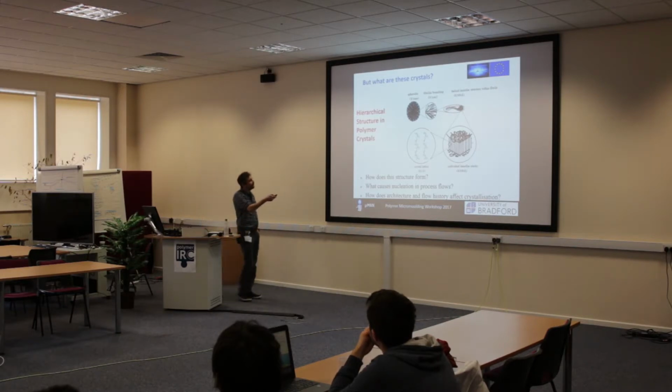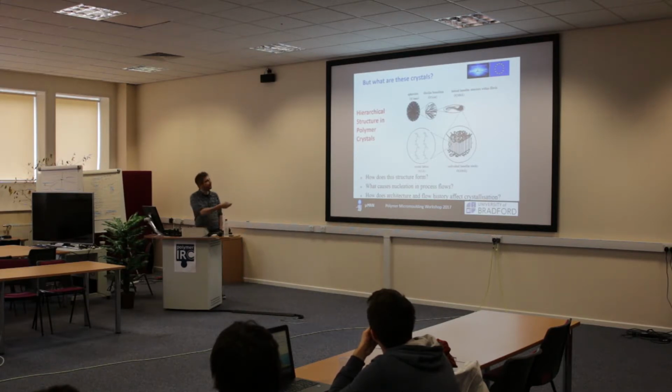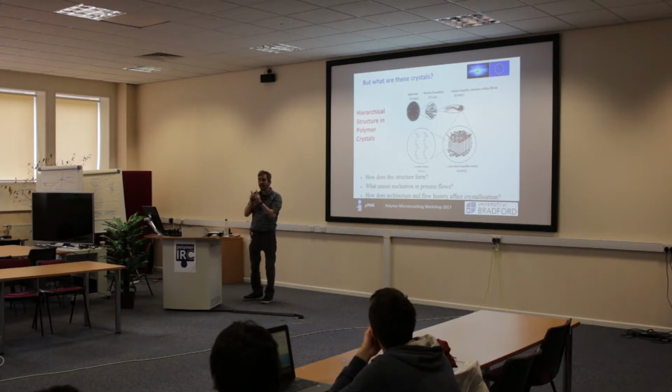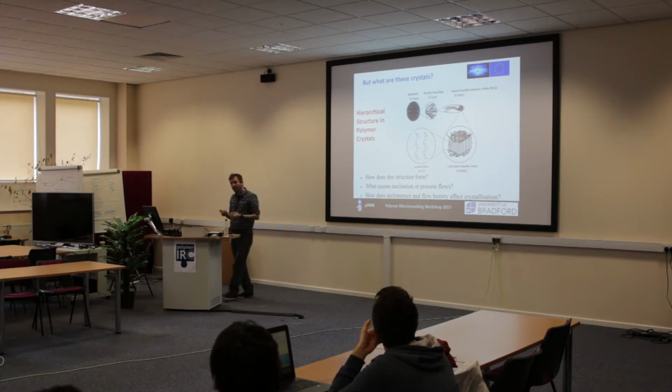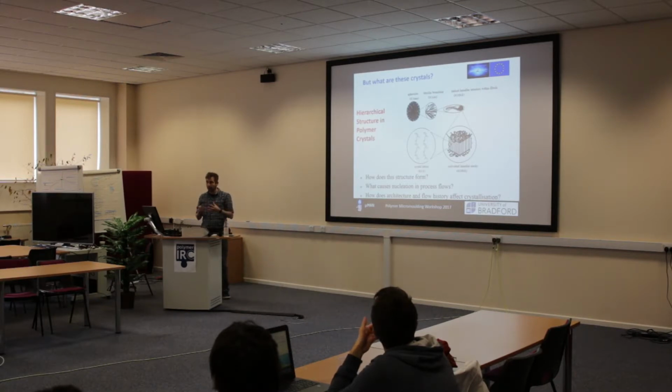We then have fibrils, we have fibrillar branching, and we have our friend the spherulite, okay? So traditionally when you see polymer crystals, that is what you will see is an image of that, which is basically a fluffy sphere with all these tendrils shooting off. The nucleation point is right in the center, and then these crystals will grow and grow and grow. Now we can control their growth, and we can control how big they get to. We can control how many of them there are through understanding our process.